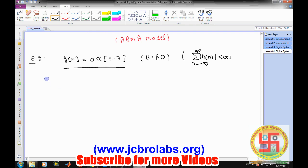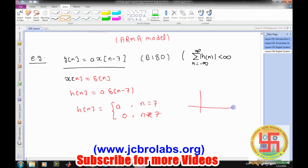So let's say impulse response means we have applied x of n as the delta signal. So in that case this y of n will be our h of n, right? So it will be a into delta of n minus 7, right? So delta of n minus 7 means if we plot it, it is equal to a when n is equal to 7 and it is 0 when n is not equal to 7. That means it exists only at n equals 7 and the value corresponds to a only.